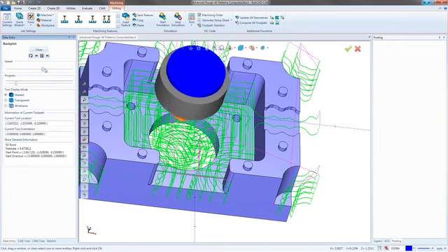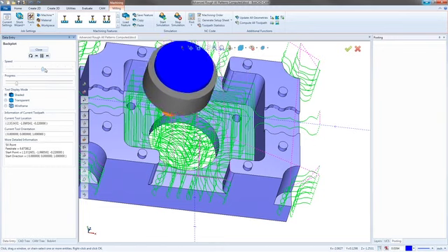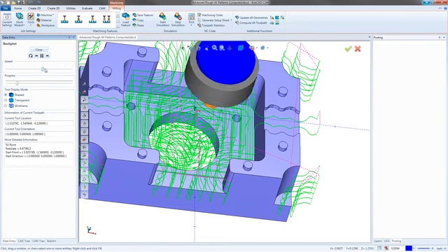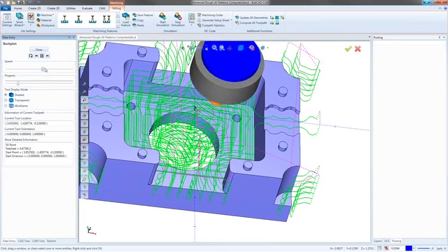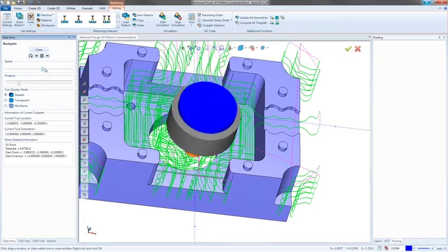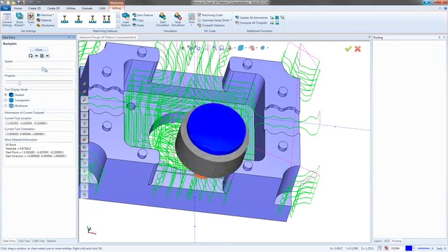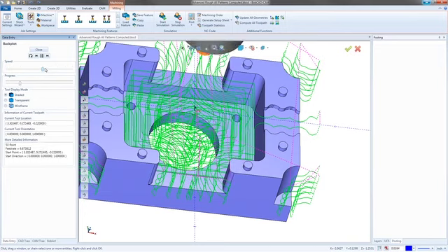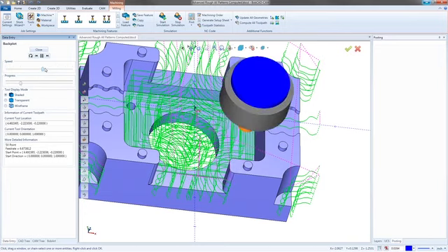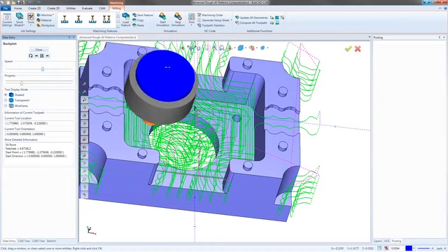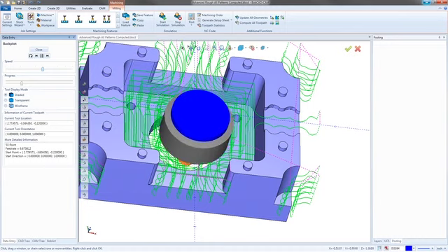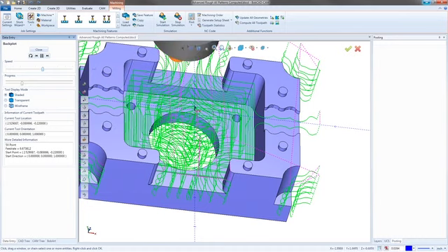And now it's going to start that spiral. So you can see that kind of diamond shape it's making off the start. And then it's slowly morphing from that inside shape that we just made. It's going to slowly morph so that it eventually matches that rectangle in the corners, but it's going to do it as an open chain after it gets rid of most of the inside geometry. That's the step we're on now. This would be all gone. So now it's just going in and climb milling those edges to kind of widen out this entire thing now.